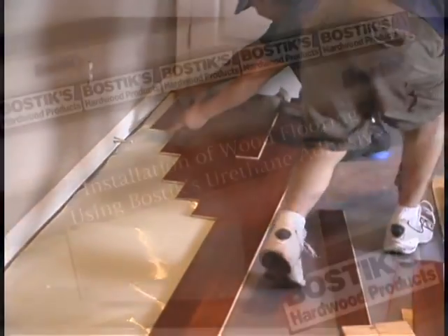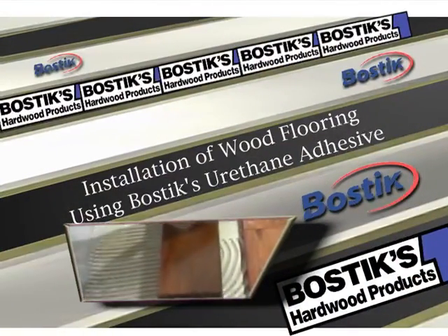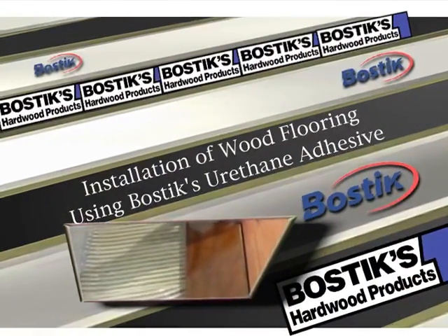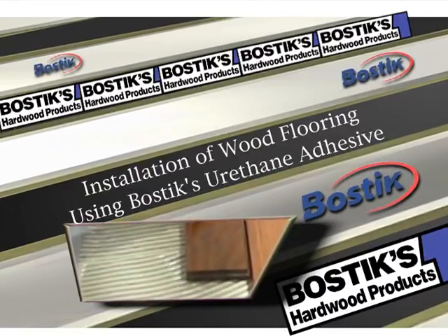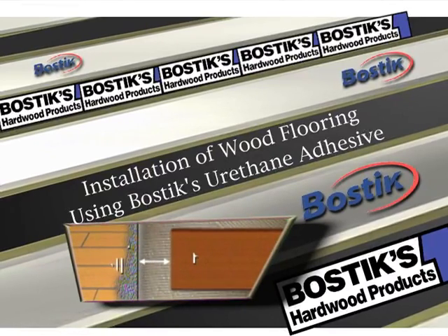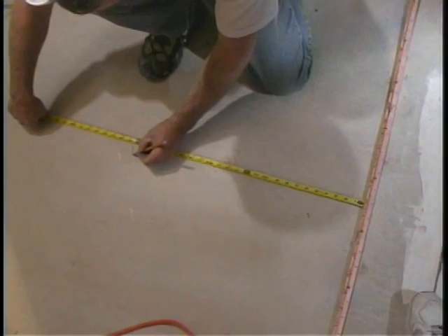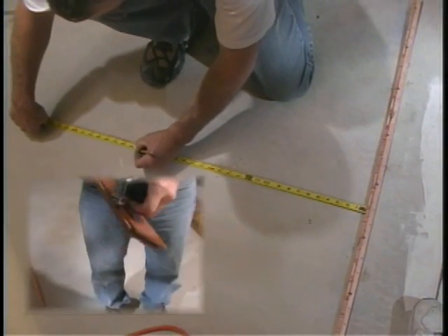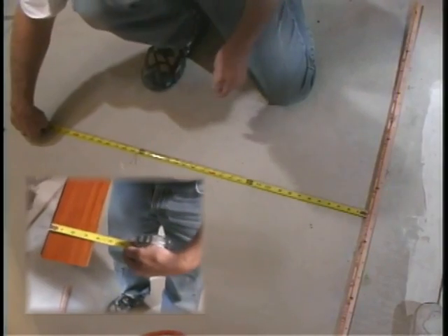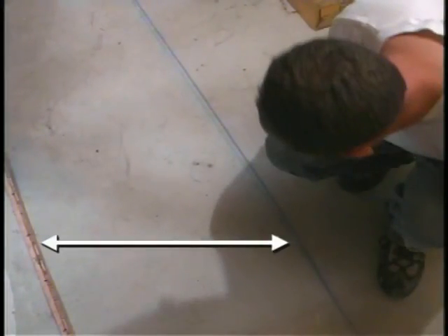In typical wood flooring installations, the first row of flooring is installed against the longest interior wall. To determine the starting point, see the wood flooring manufacturer's recommendations for required expansion space. In our installation, we measured out from the starter row to a point equal with a multiple of the board width and snapped a line. This is the first section on which we'll spread the adhesive.